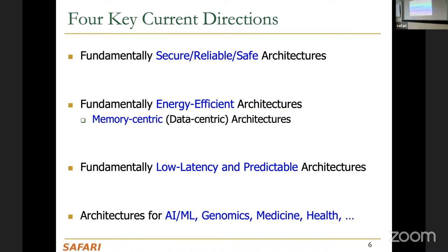More recently, we had a paper at Micro. Rahul drove this idea. If he was there, he could give a lecture on that. But basically, the idea is to predict which load requests are going to miss in the on-chip cache hierarchy, so that you can start the request early. Today's on-chip cache hierarchies have L1, L2, L3, L4 caches. They're huge, and it takes a long time to query those caches, around 50 cycles or so, maybe more in the future. Can we somehow predict that a load is not going to find its data in any of those caches, so that we can start the main memory access earlier?